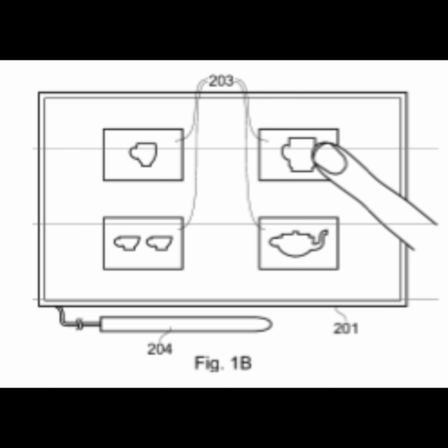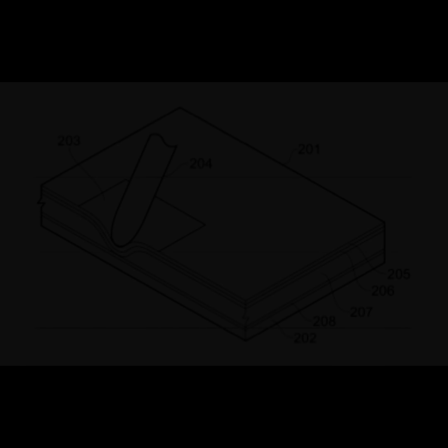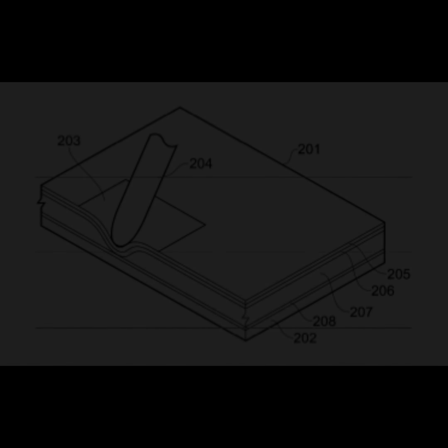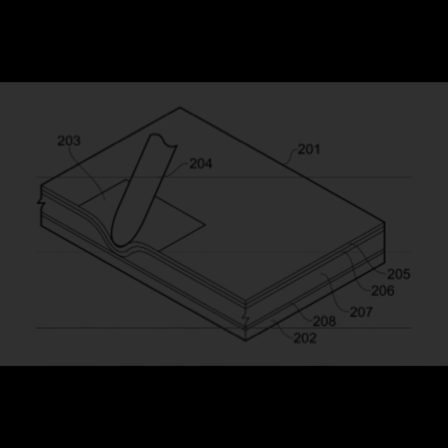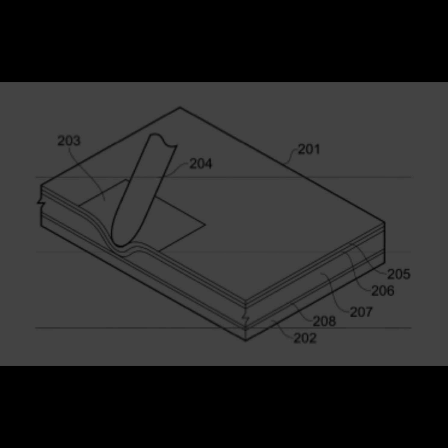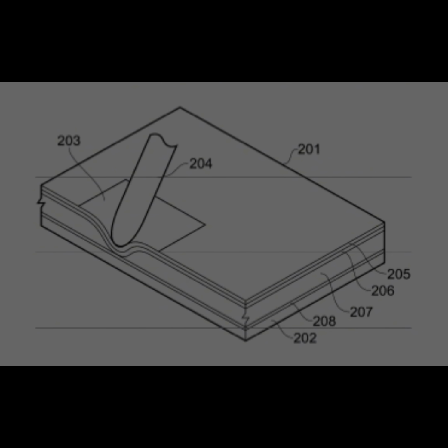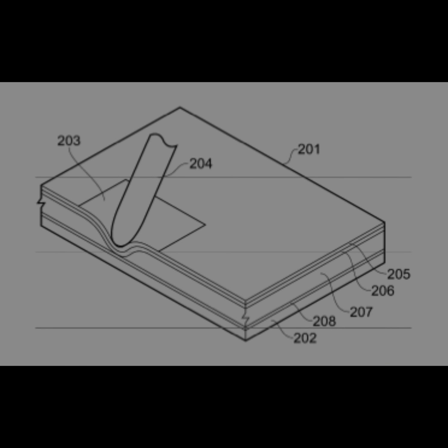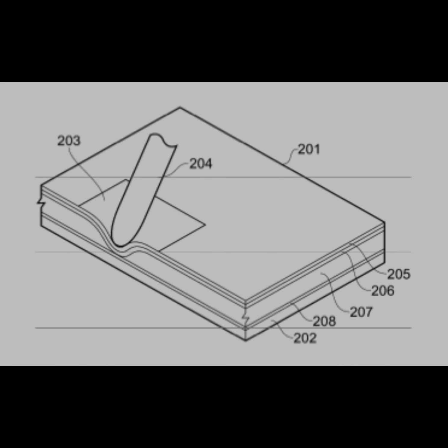During each first time period T1, a voltage minus V is supplied to contact A, a voltage plus V is supplied to contact B, and contacts C and D are disconnected from the voltage supply. During each second time period, T2, a voltage minus V is supplied to contact C, a voltage plus V is supplied to contact D, and contacts A and B are disconnected from the voltage supply. In this way, a first predetermined voltage distribution on the resistive layer during the time periods T1 is alternated with a second predetermined voltage distribution on the resistive layer during the time periods T2.